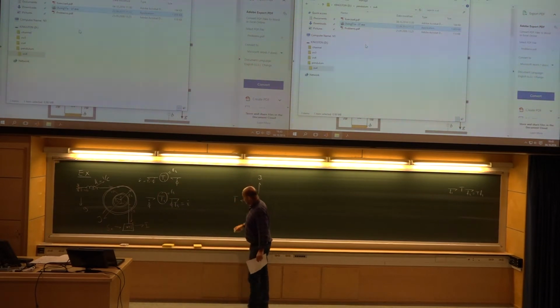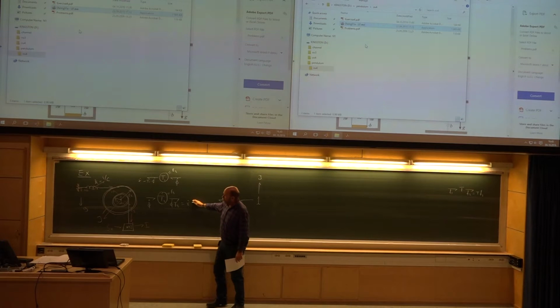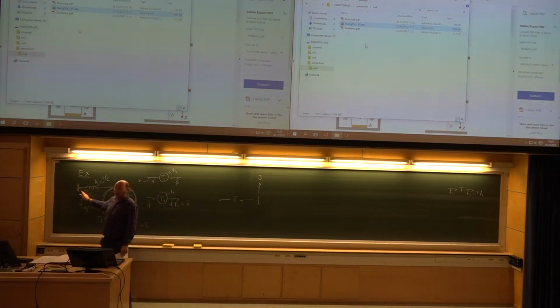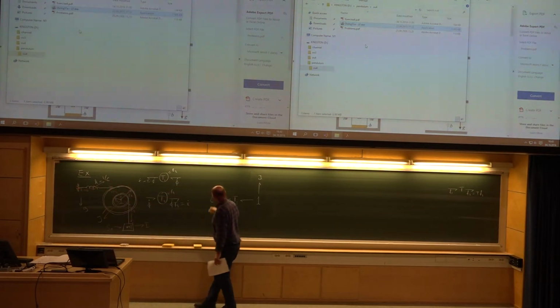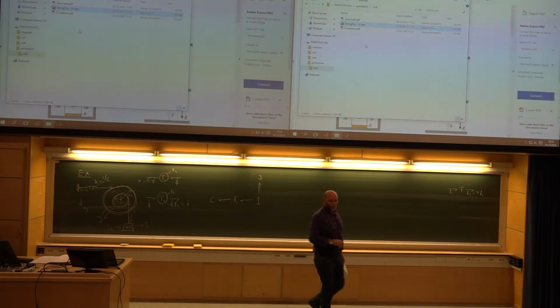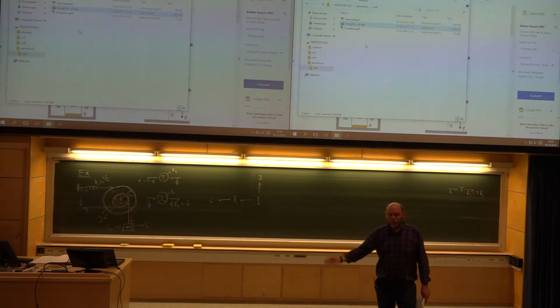There I have the transformer number 1, and continuing, finding actually a 0 up to a spring C, and then continuing to the 1 junction with 0 velocity. But now you should be experienced enough to see, okay, it's 0. So I can just go straight to a C element. If you're in doubt, of course you can do it the long way, a 0 up to a C and then another 1 junction, and then simplify it afterwards. The result should be the same.